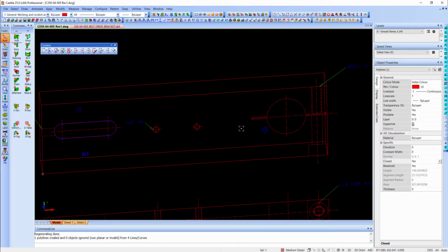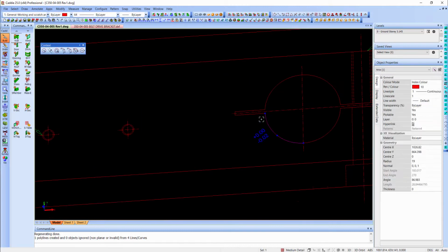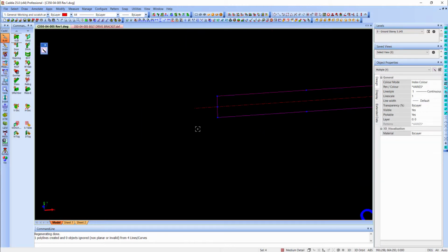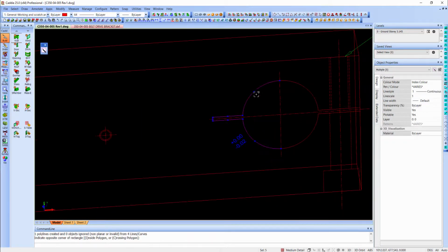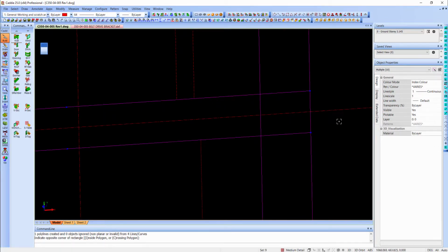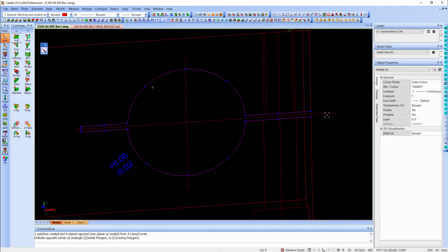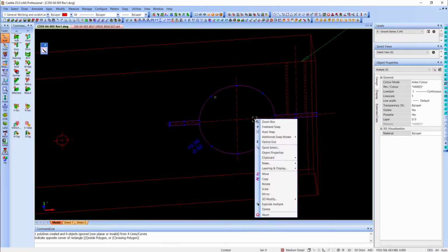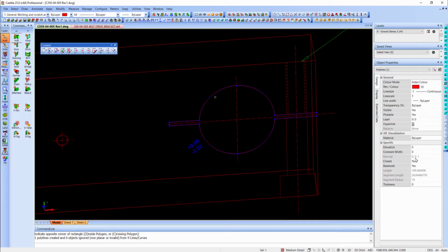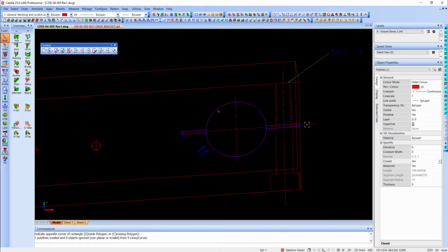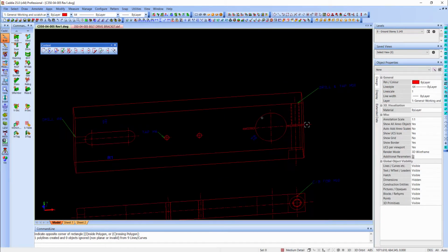These next two we're going to do differently, I'll show you now. So let's go for the last one. This one has got a little trick to it. You'll notice the endpoint will not close up. When I select the end object, as you can see here, it selects a whole different object. So I'll unselect that, still continue, right click, make polyline from lines and arcs, select that. Now you'll see the property is closed no. Select yes, and it will close it up automatically.